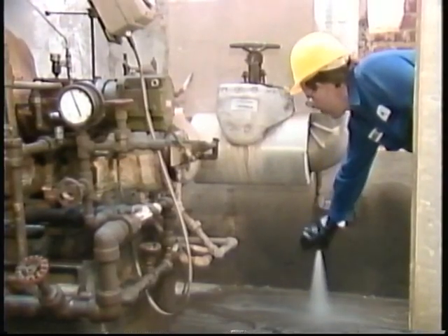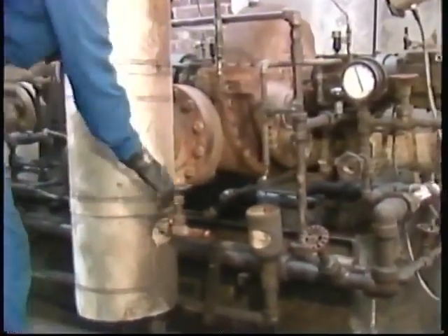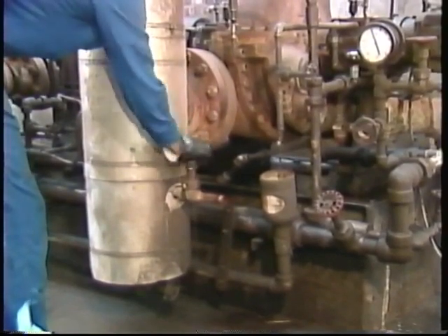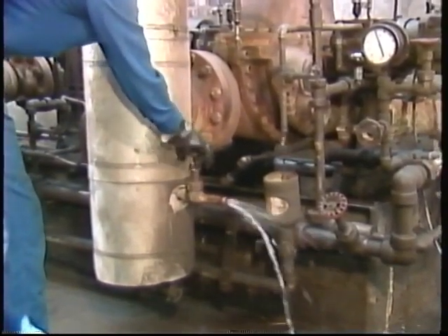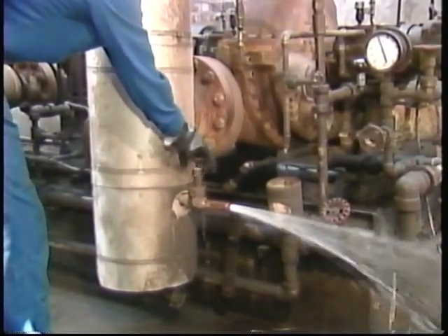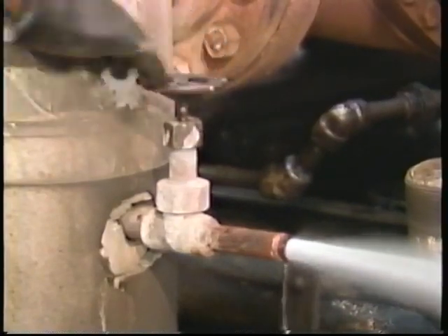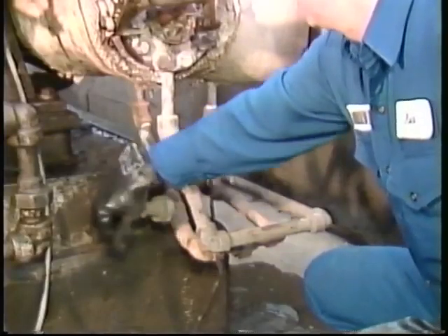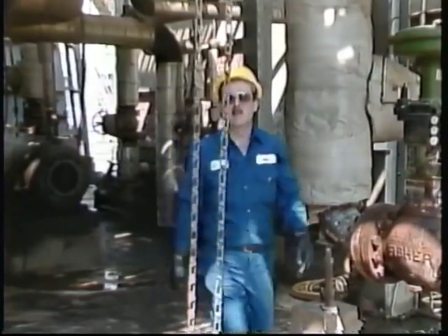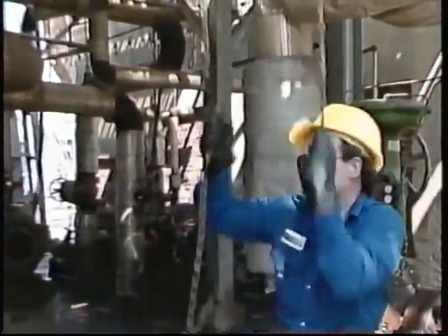One especially important preparation for virtually any steam turbine is to completely drain any condensate from the turbine and its lines before startup. High-velocity slugs of condensate on the rotor during operation can be very dangerous and damaging. To drain the turbine, open the drain valves for the inlet piping, the casing and steam chest, and the exhaust line piping. Then steam is admitted into the turbine by slowly cracking open the block valves in the exhaust line.